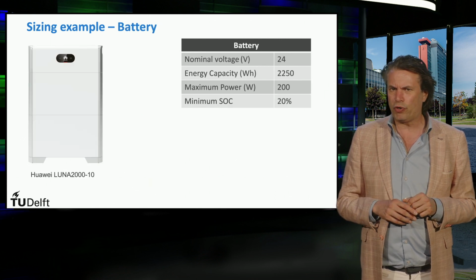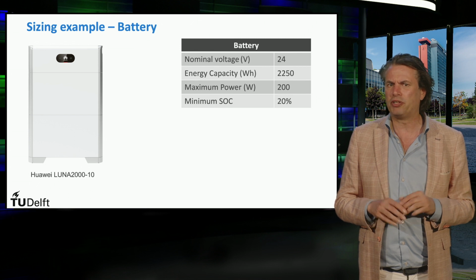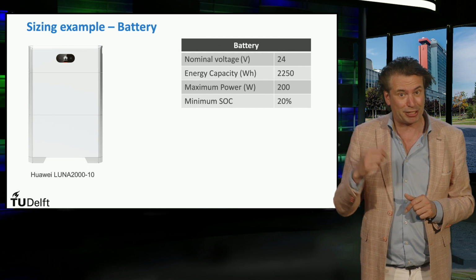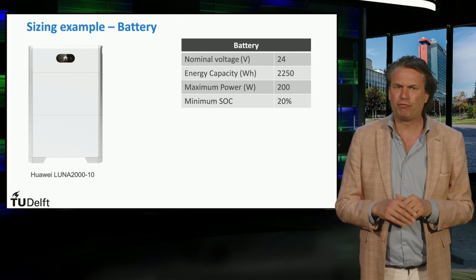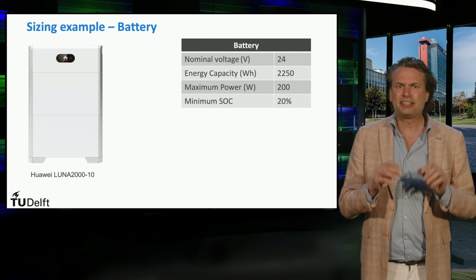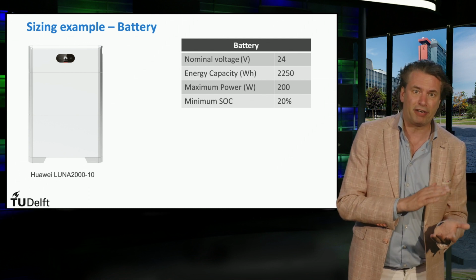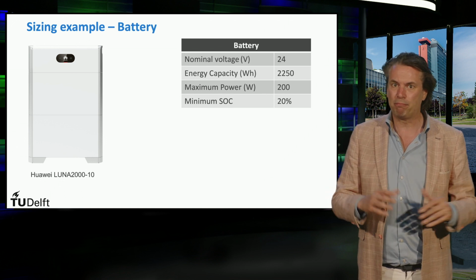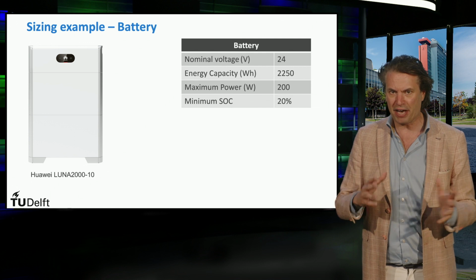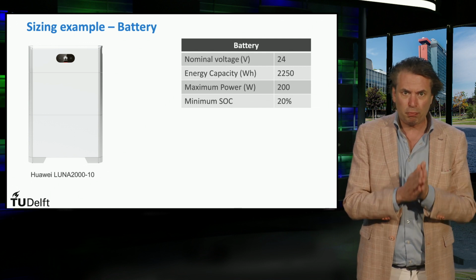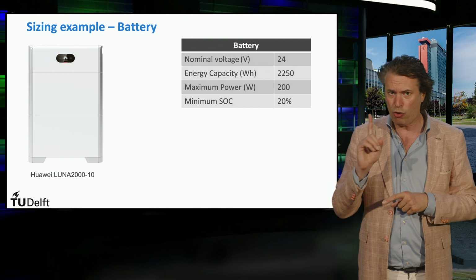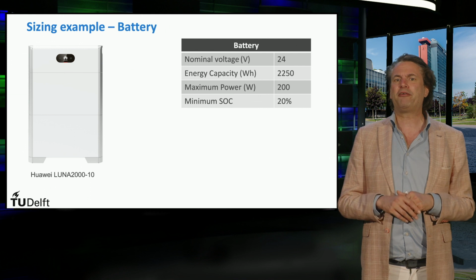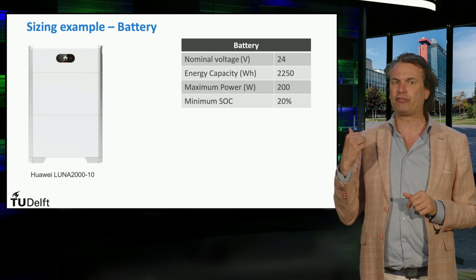Now let's move on to the battery. Let's assume an arbitrary battery that is given with the specification as shown here. The depth of discharge, or the DOD, is the depth until which the battery can be effectively used. We must now choose how the battery bank must be configured. That is, how many batteries of the given specifications should be there in the battery bank and how should they be interconnected. The minimum battery bank capacity can be derived as follows.